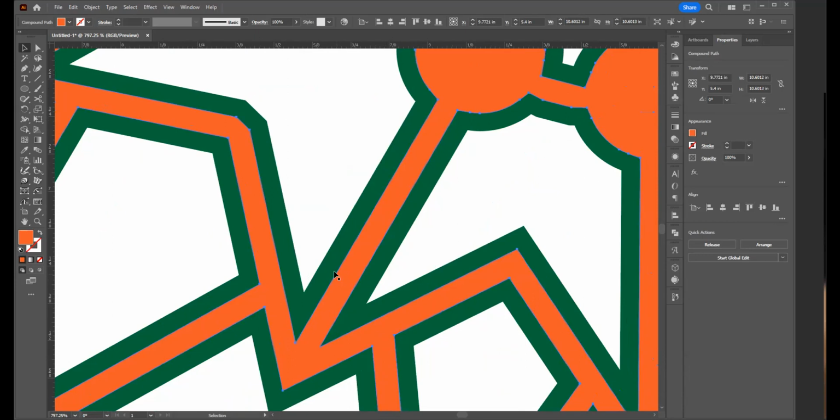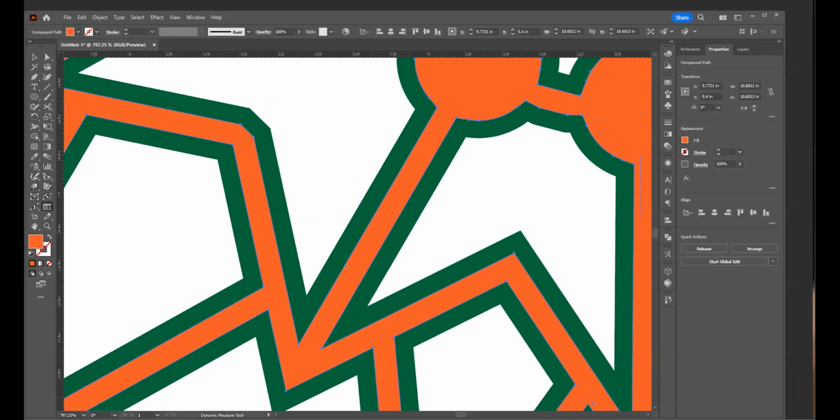So one of the other tools that Astute has is this measurement tool. You click it and you can take the little square, select a spot, and drag across the line, and you can see that this is 0.07. So if we did a 0.06, there would be hardly anything there, and that's why the 0.12 is just a little bit that's left.